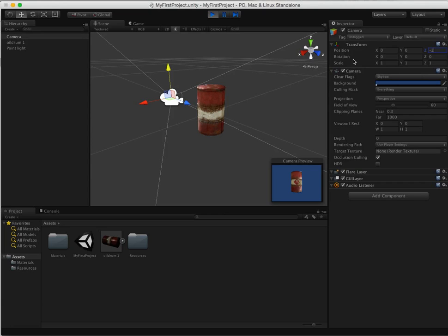Well, we can rotate it. So we can use the dialog again to specify in degrees the rotation around each of its own axes. So if I put a 15-degree rotation here, then it's rotating around the x-axis. That means the camera is now pointing downwards along the axis here.